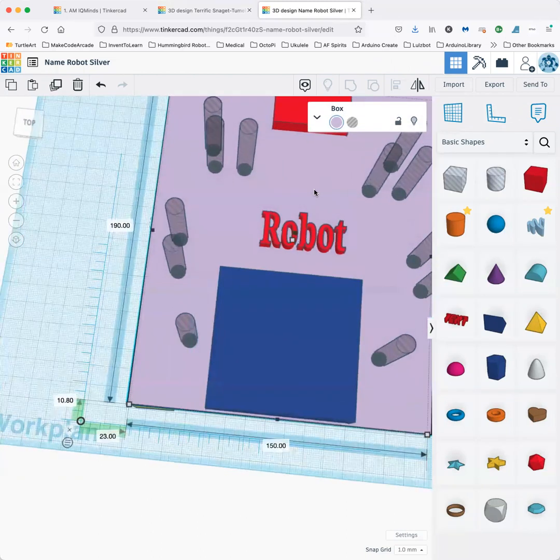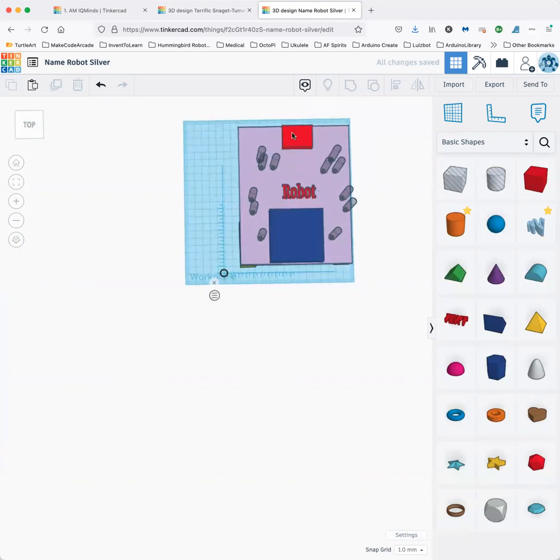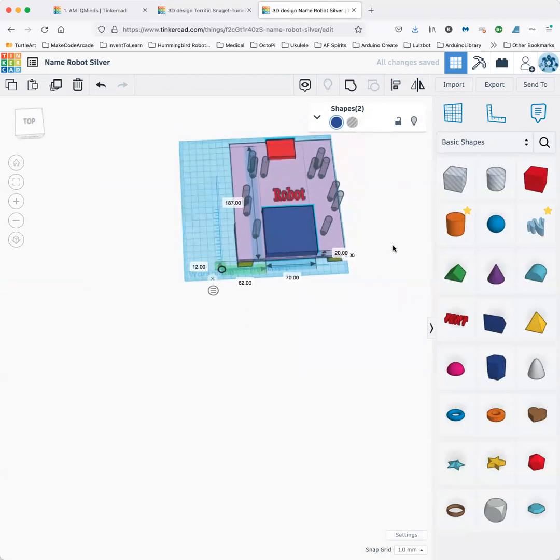And up at the top here, I have just a rectangle that's 40 by 29. And it could be 40 by 30, it doesn't matter that much. It probably got moved a little bit in resize. We're going to have a little tiny breadboard that we put our ultrasonic distance sensor in. So that's what that is for. If I wanted to center those, which isn't entirely necessary, I could click on one, hold the shift key down, click on this one, and align them with each other.